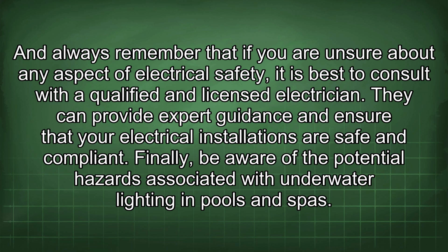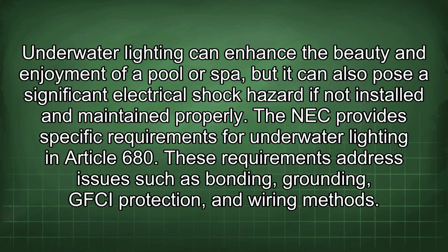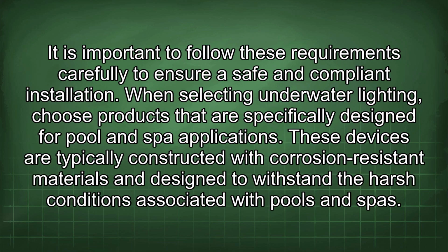Finally, be aware of the potential hazards associated with underwater lighting in pools and spas. Underwater lighting can enhance the beauty and enjoyment of a pool or spa, but it can also pose a significant electrical shock hazard if not installed and maintained properly. The NEC provides specific requirements for underwater lighting in Article 680. These requirements address issues such as bonding, grounding, GFCI protection, and wiring methods. It is important to follow these requirements carefully to ensure a safe and compliant installation.